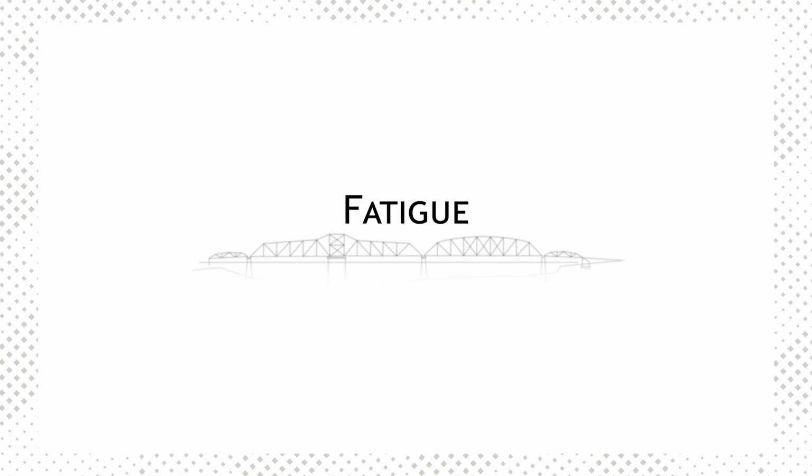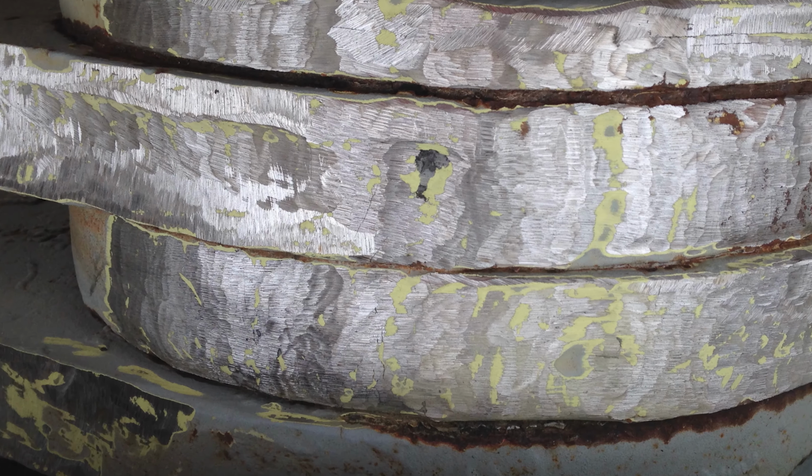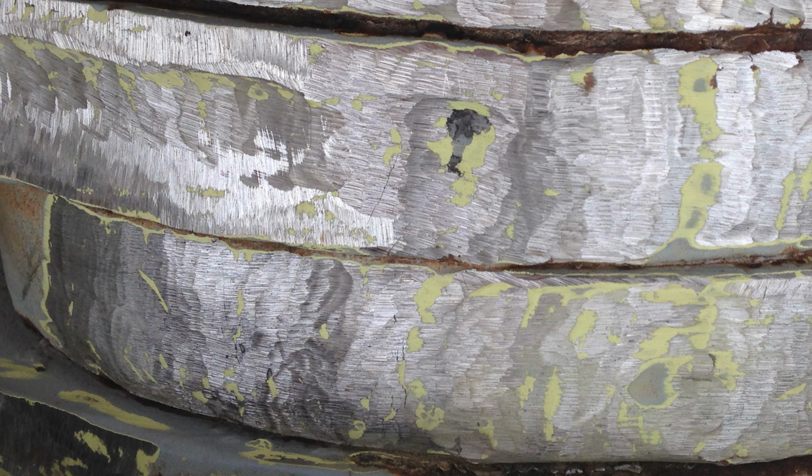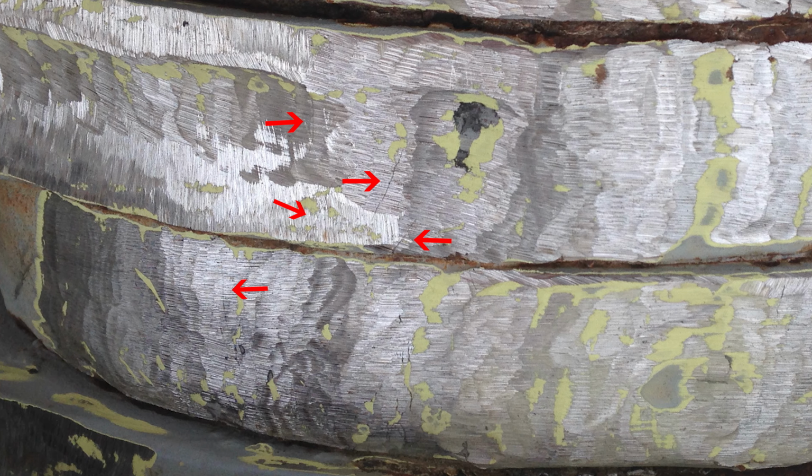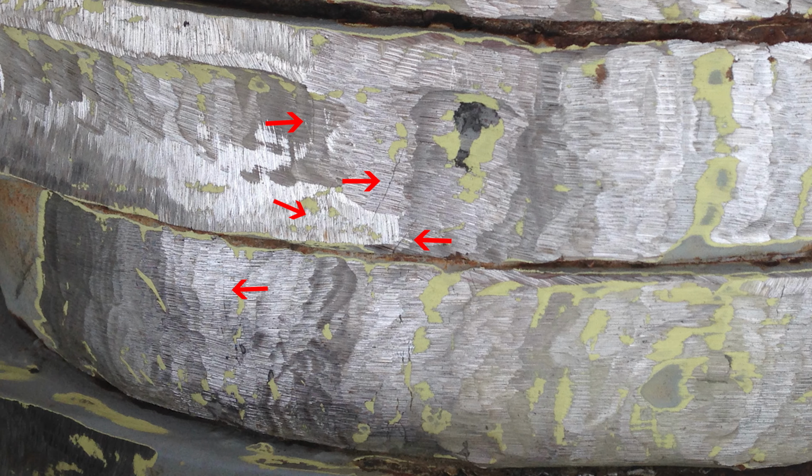Fatigue is when a bridge is loaded at a level below the yield strength. It's not loaded that heavily, but it's loaded many times. Like when a truck goes over a bridge, there's going to be vibration, and there can be thousands of trucks going over a bridge. So you might get a small crack, and that crack, for the majority of its life, is going to be really small. You're not even going to see it. In fact, it might be under the rivet head or under the bolt head, and then it can propagate, just get a little bit bigger. The life of a crack spends most of its time being very small.